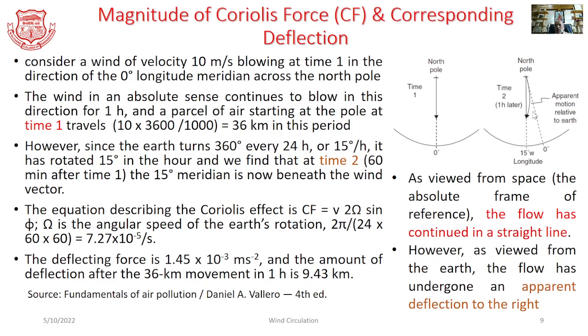So 36 kilometers into 15 degrees into pi by 180 degrees will help us to work out that deflection as 9.43 kilometers.